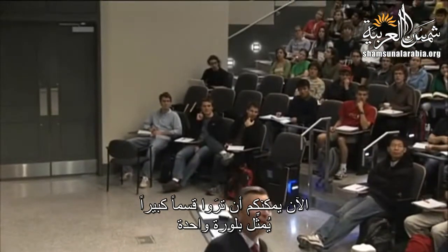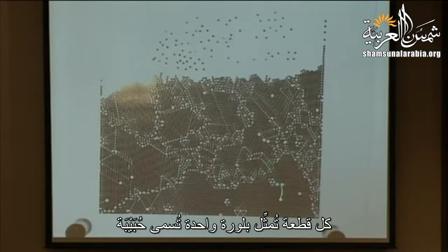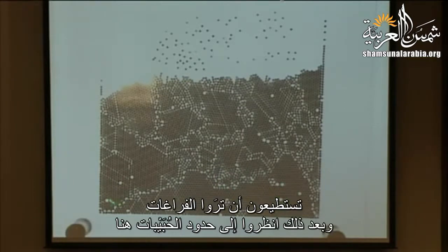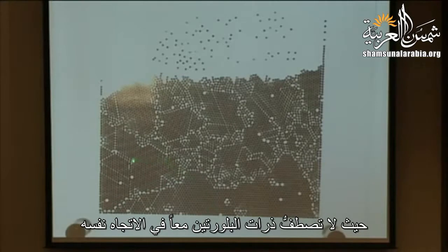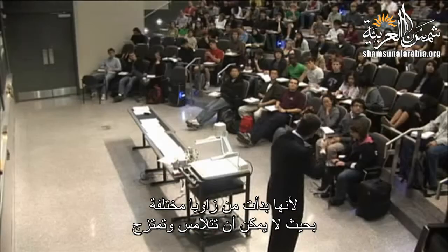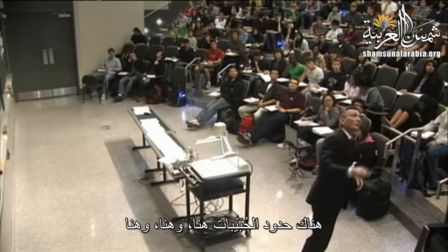Okay, so now you can see a large section here of a single crystal. Each one of these is called a grain. A grain is a zone that is a single crystal with some defects. You can see the vacancies, and then look at the grain boundary here. See, this is a nice crystal, this is a nice crystal, so one grain, two grains, and there's the grain boundary where these don't line up with those because they started from a different angle, so they can't impinge and blend. So there's grain boundaries here, here, here, and there's, oh, beautiful stuff.